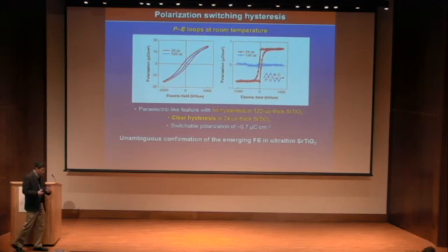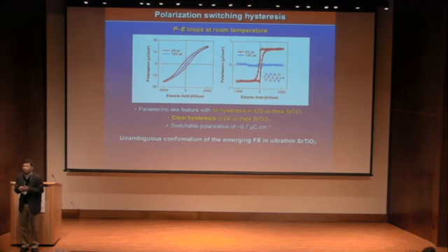And then finally, we want to test this with electrical measurement. It's very challenging because the thickness is only 12 to 24 unit cells, extremely thin. So leakage is very big, and that's why atomic layer controlled growth without any pinholes is very important. So we made a device of about 5 micron diameter, which is a very, very small one, and we patterned this device with ion milling.